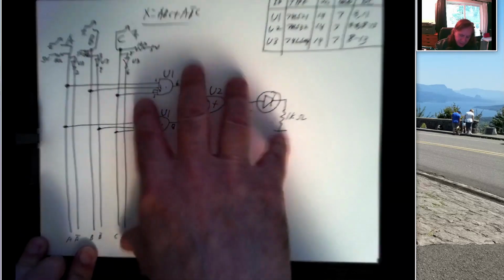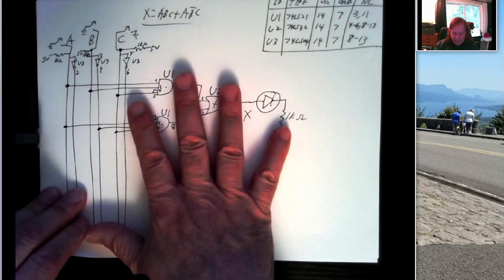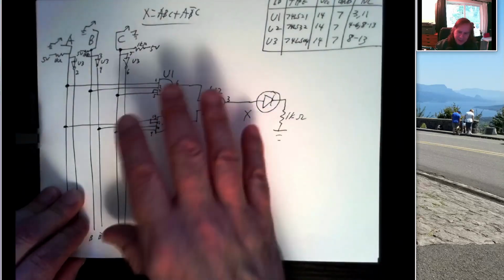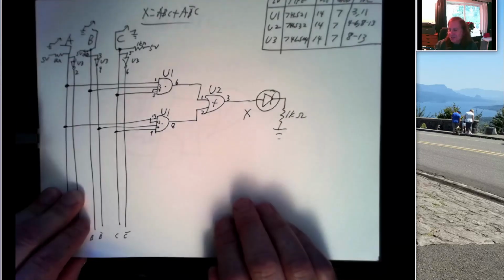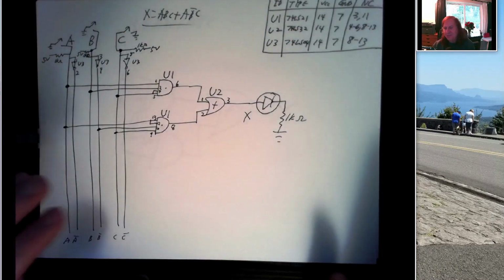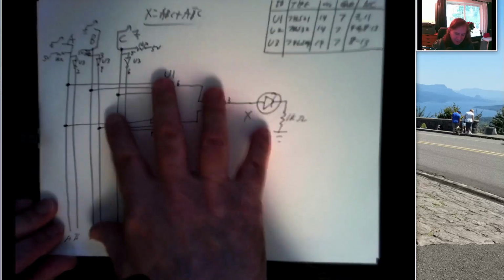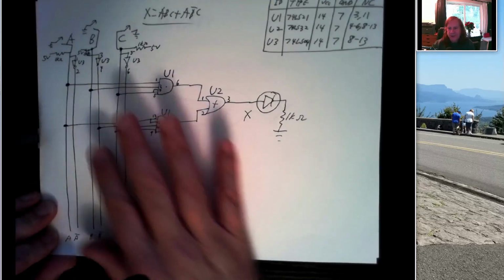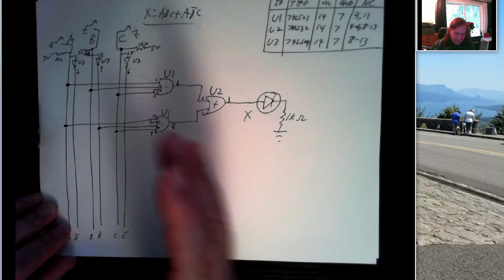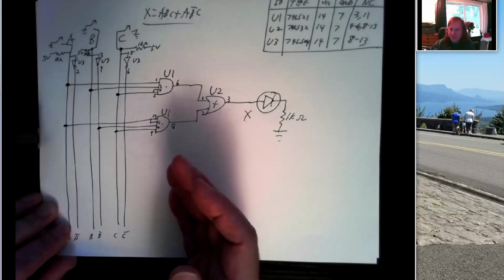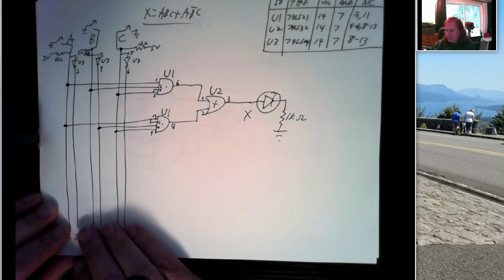So this is really, really important. Anytime that you are building a circuit and it's not doing what it's supposed to do, and you ask someone for help, the first thing they're going to say is, let me see your wiring diagram. If you don't have a wiring diagram, there's no help, right? You got to have this written out before you can debug your circuit.